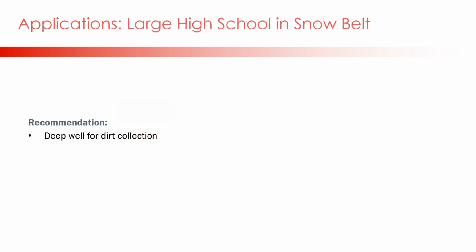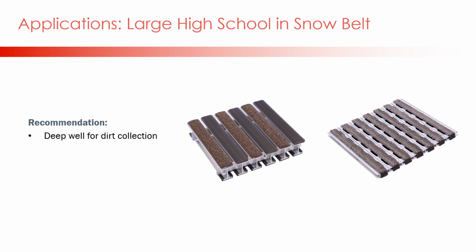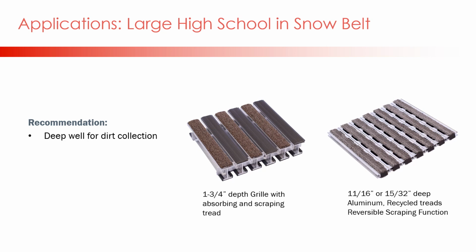With these considerations, potential snow, high traffic volume, low loads, and weekly cleaning, two options are recommended: an aluminum grill with tread inserts or the recycled treads linked with alternating aluminum rails.